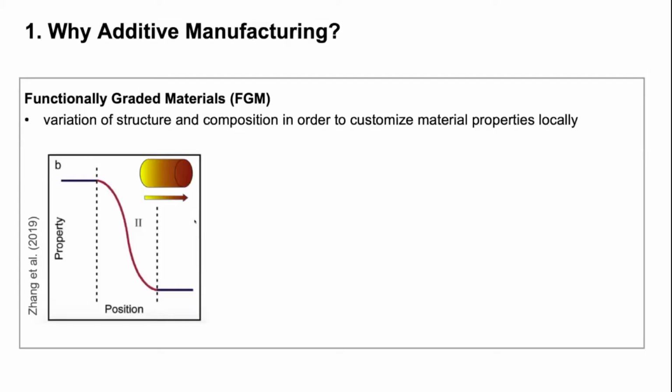There are several reasons to use additive manufacturing. The first, which is often mentioned, is that this process is cost-effective for small lot sizes, so we can individualize products. We do not need to adjust a manufacturing plant for one specific individual product. This is an advantage over casting, for example, or other metal cutting strategies.